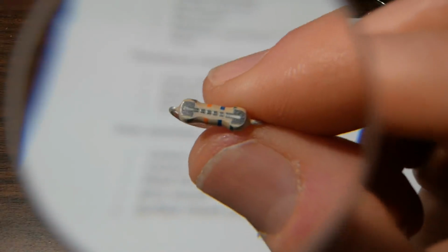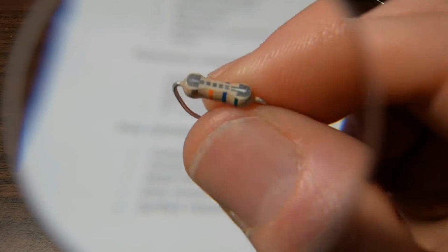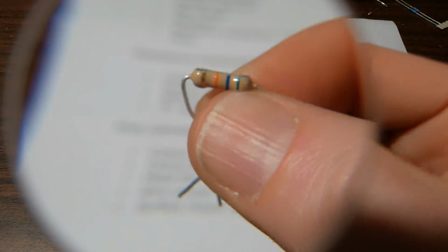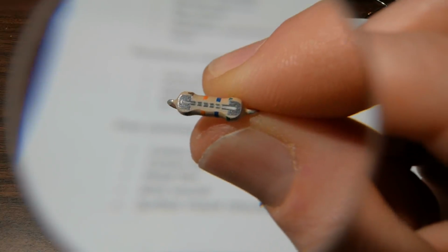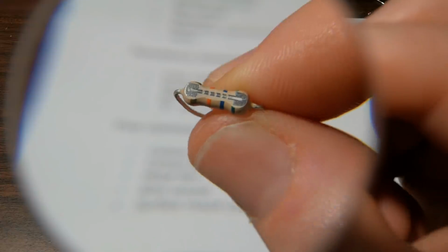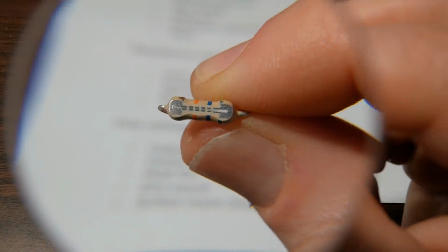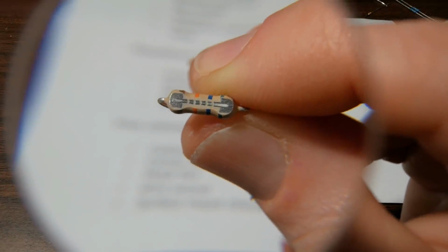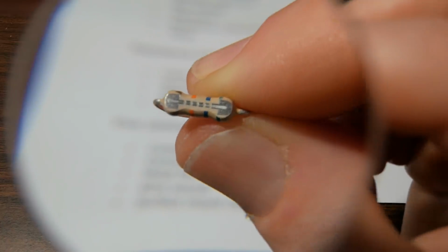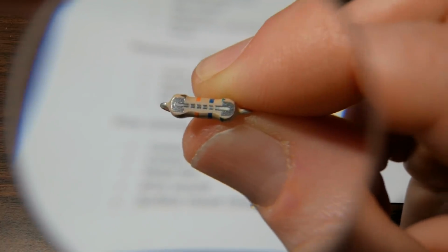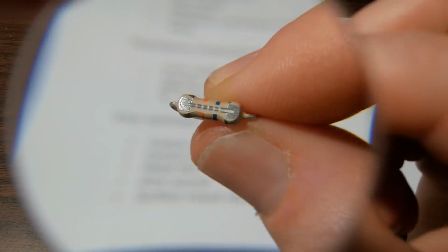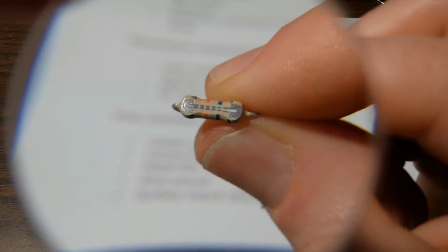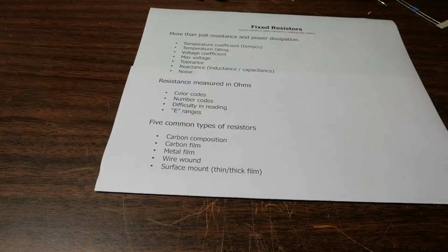Let me put a magnifying lens in front of the camera here. We can get a close-up of a carbon film resistor. I've taken this one and sanded down one side. You can see the metal end caps. You can see part of that spiral of carbon. And the white line you see towards the right, that's probably the ceramic cylinder that the carbon is laid on when they make that spiral. So yeah, that's pretty neat. You can see how the resistor is constructed.